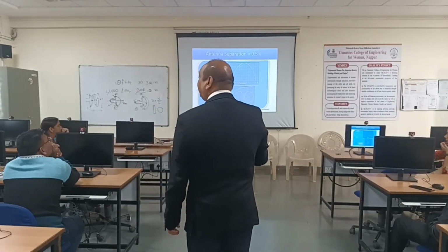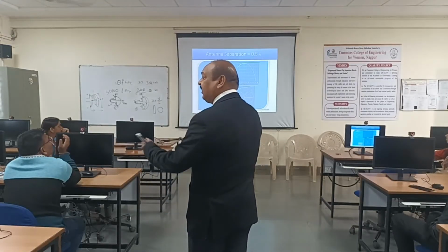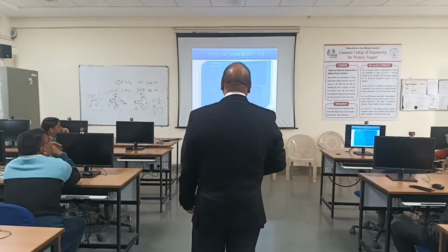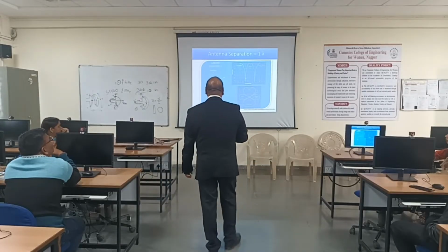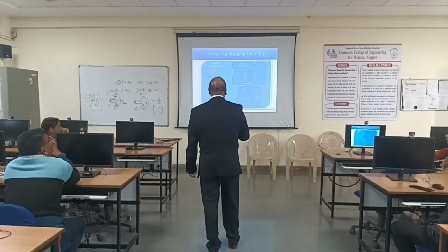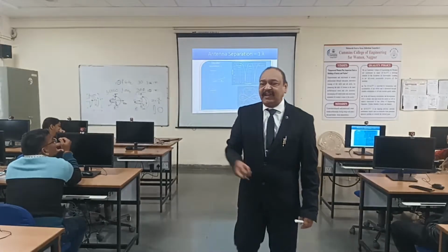Okay, and that is the best radiation pattern. If you increase further, then side lobes start gaining. Next, if you increase the distance to lambda between the two dipole elements, then you will not get the one main lobe, but there are two secondary lobes, and the radiation pattern will be like this. This is the main lobe, and this is the secondary lobe you will get. The secondary lobe is not designed. That can be known as side lobes.